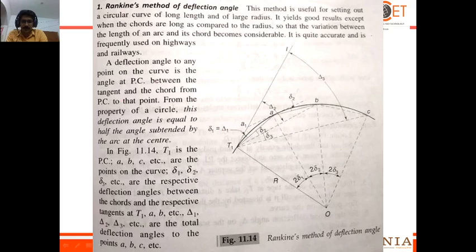the deflection angle. So we have already seen about the delta deflection angle at the point of intersection. Is there any relation? We will see. See, this deflection angle is equal to half the angle subtended by the arc at the center. Say there is an angle formed at the center, by the radius to T1 and T2. There one angle will be formed. It is equal to twice the total angle from the tangent to the full long chord, right?